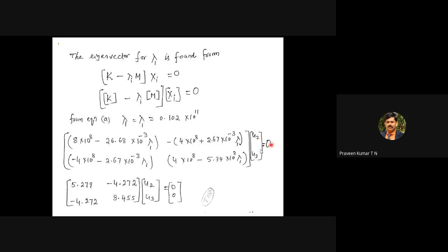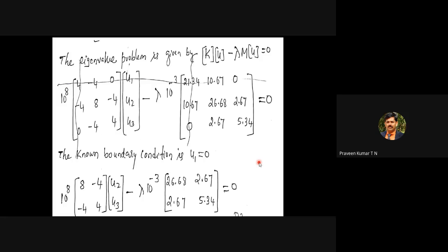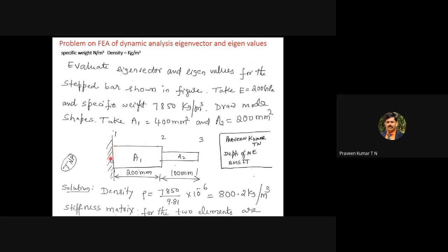Now you are not going to find out what is the value of U2 or what is the value of U3. Instead, when U2 is displaced by 1 mm, what is the displacement of U3? If we come back, because you have to understand some concept here. Imagine node 1 is fixed, which means no displacement. Your U1 is equal to 0, there is no question here.